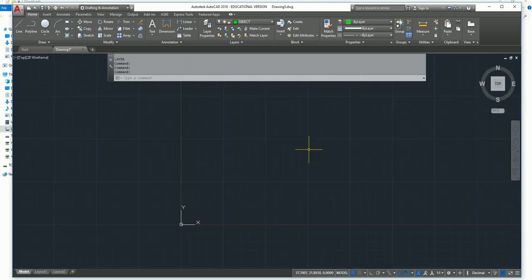Put it back. So I want everyone to draw another rectangle. Type in REC, and this time start it at 0, 20. I'm just showing you this because Jordan actually did it by accident, so you don't freak out when your drawing's not showing up. Then hit the @ symbol, shift 2, and then 20, 20, enter.